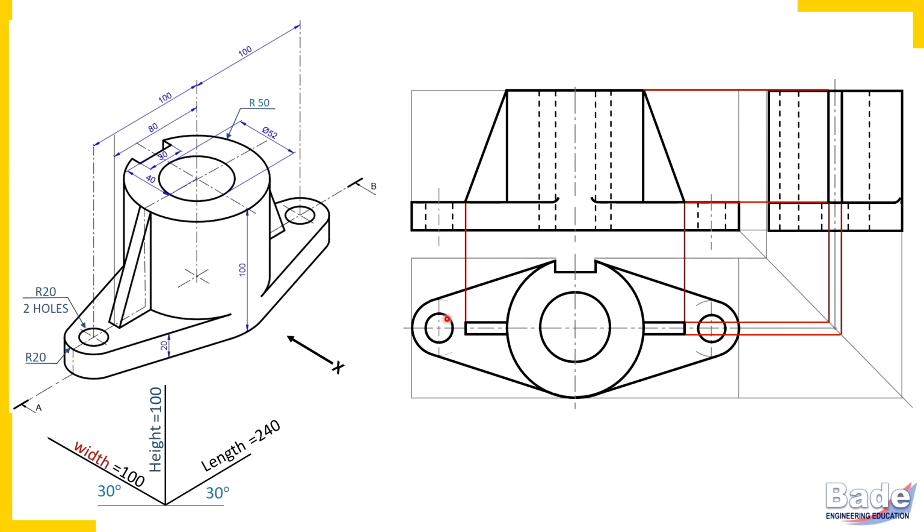We have completed this drawing, but actually in this topic we are going to study sectional view. We are asked to draw the sectional front view. Also these two arrows suggest to you that the section is visible from the front, and the portion nearer to the observer, that is of course the front portion, is to be removed.